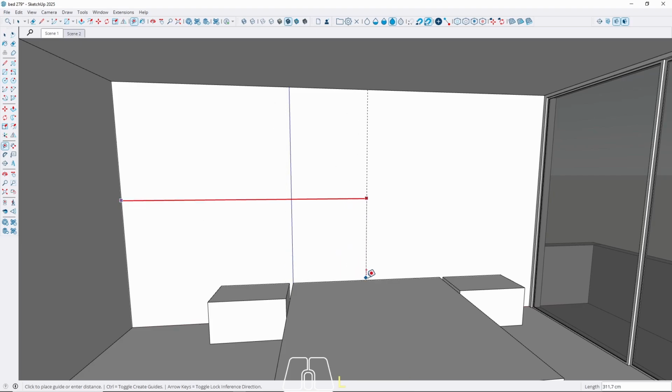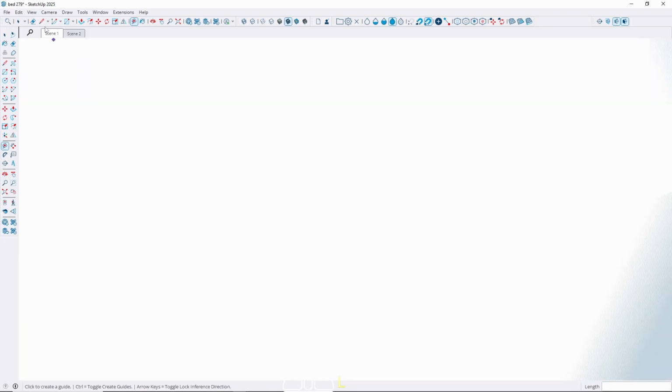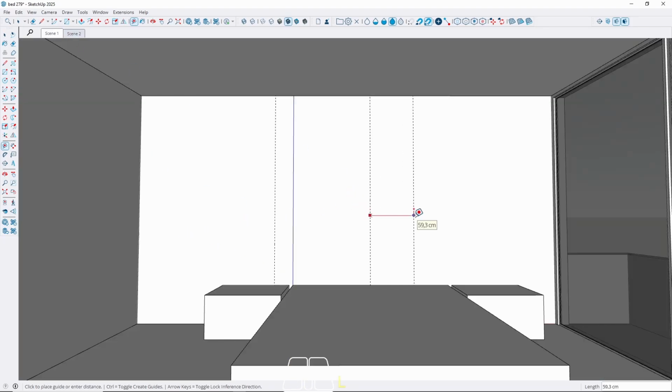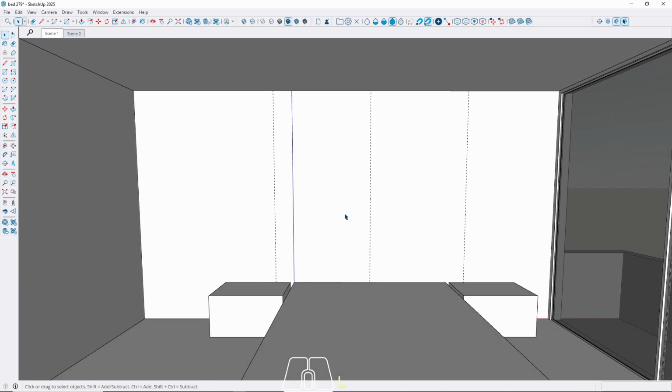Let's take the center point of the bed firstly, and then we have gap to the side table 110. Let's offset it to 130 and 130. Okay, and then I think usually bed head has 100 height for the bed head.